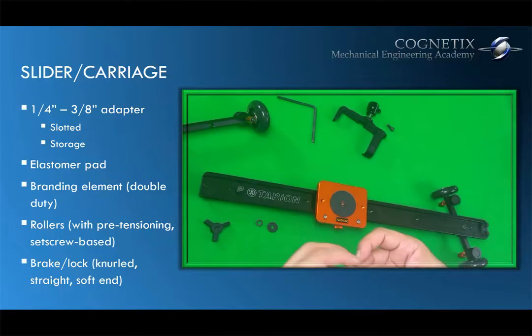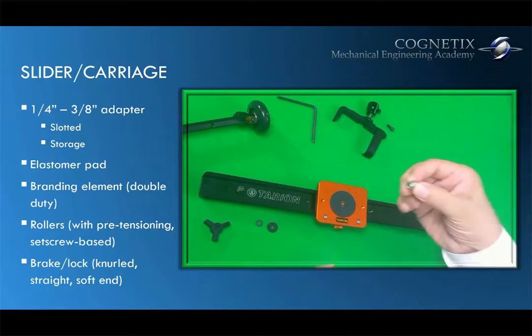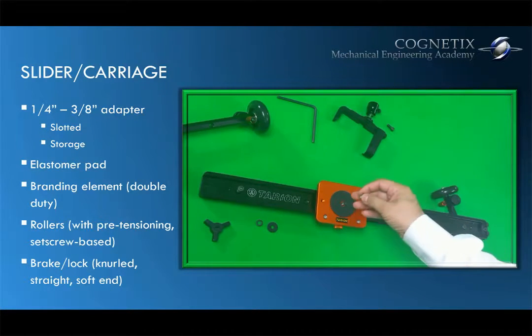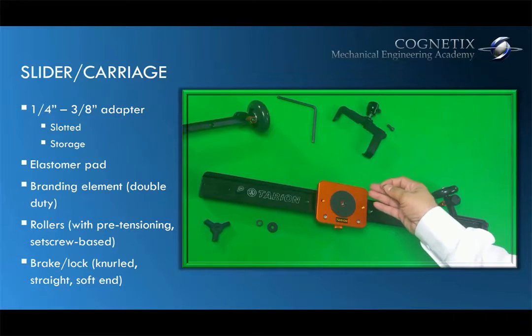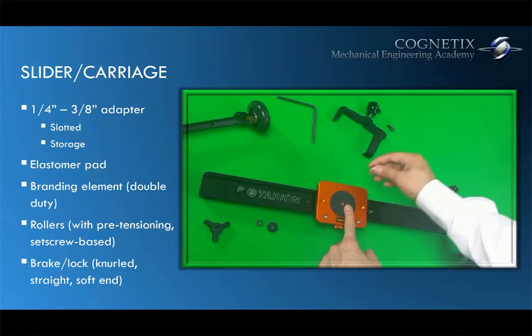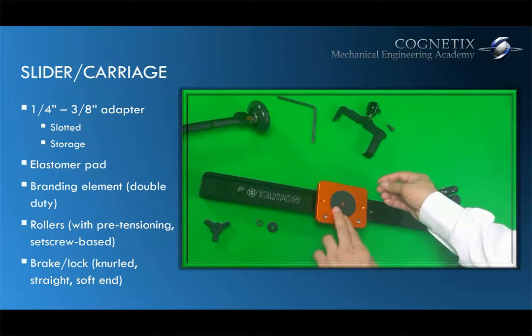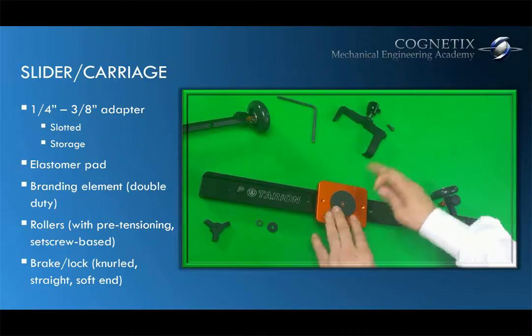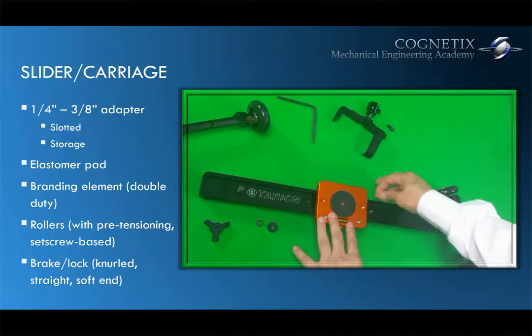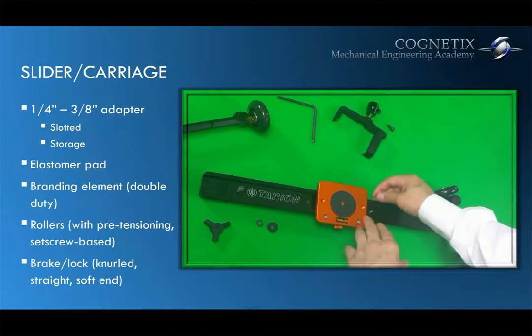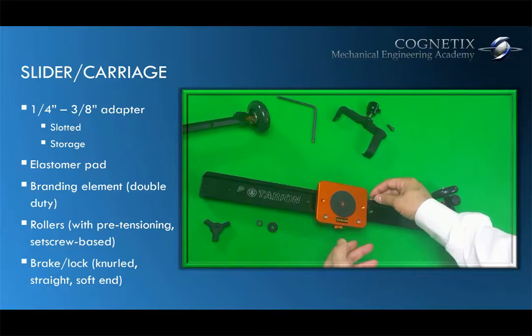Product designers, we have to think about such things. Whenever possible, either the removable component is somehow attached to your product, let's say it had a string and it just hangs off to the side, you cannot lose it because it's connected with a string. Okay? In this case, that doesn't make sense because it would be rattling, it would hit metal to metal, it would make noise, and that would affect the quality of your video recordings.